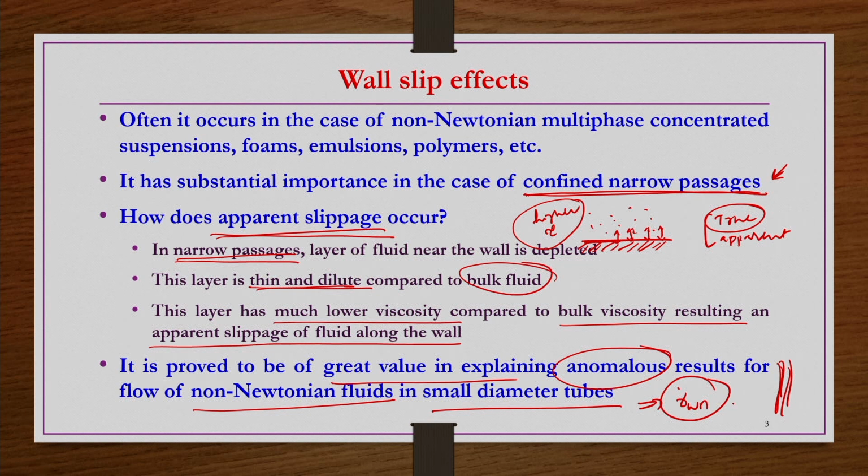Then again we can see that after incorporating the wall slippage, the shear stress versus apparent shear rate information obtained by using different capillaries does not show different curves; all the curves would superimpose onto each other. Okay.